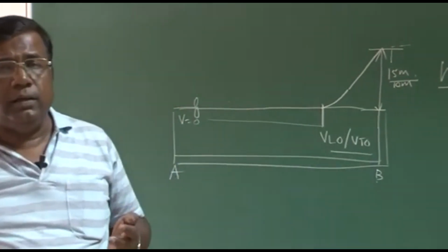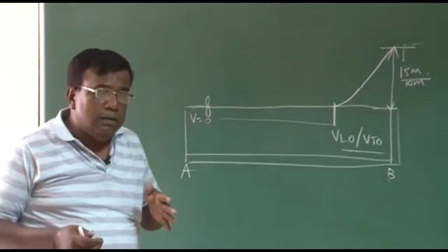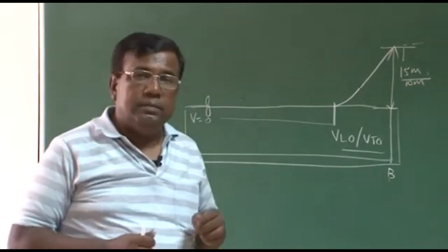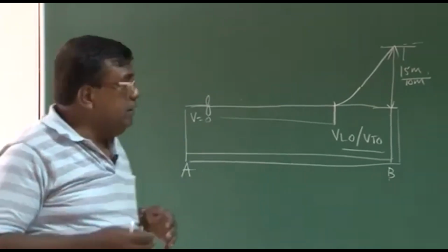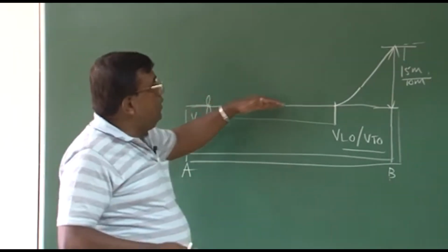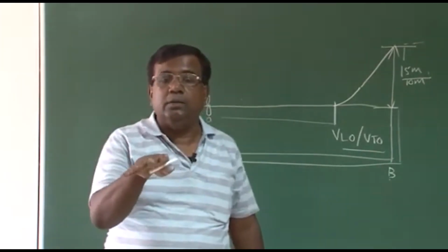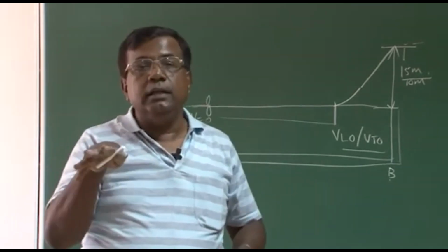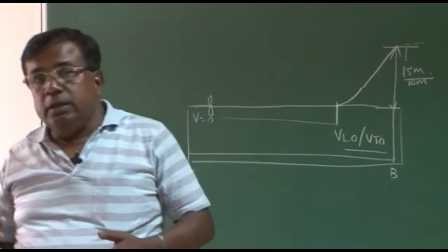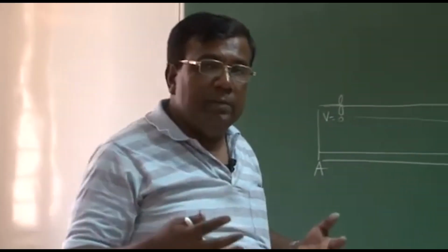For example, at what speed the elevators will be effective, at what speed the rudder will be effective. Imagine on the ground, I want to steer the nose wheel. I want to turn on the ground. How do I do that? I use the rudder and turn the nose. But for the rudder to be effective, there has to be some defined speed.